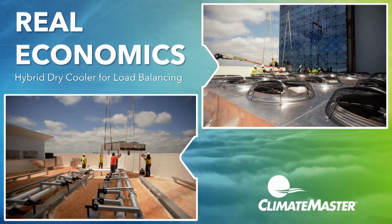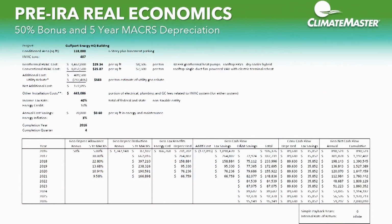The dry coolers don't do anything in the summer. They just sit there. They're not adding to peak demand. They're not affecting anything. They only operate if it's below 50 degrees outside. And we even turn them down during the day so that the people in the offices don't have to hear them. We don't turn them off. We just slow them down.